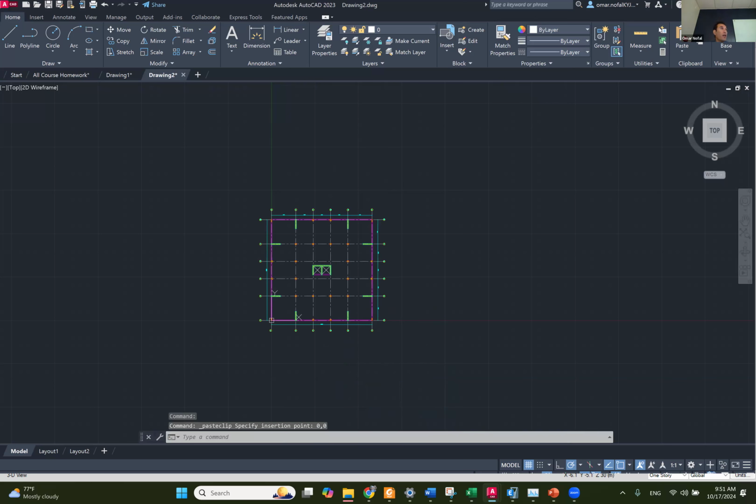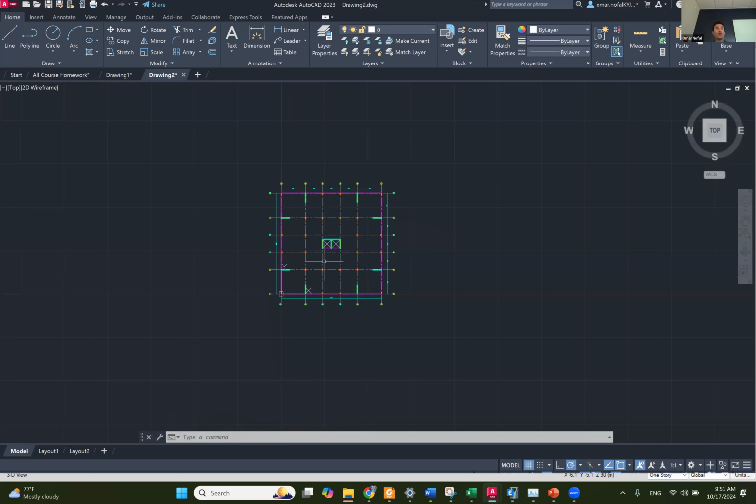All right, so actually I can import this to ETABS right now, but I'm gonna do a little bit of modification to this model. The easiest and fastest way to draw your structure in ETABS by importing an AutoCAD file is that you need to have the column locations, the rectangular areas, as a polyline. If you make it as broken lines, the software is not gonna see it as a column, just some broken lines. But if the lines are all connected as a rectangle, ETABS can see it as a column. When we tell ETABS this layer of AutoCAD is a column, it's gonna see it.